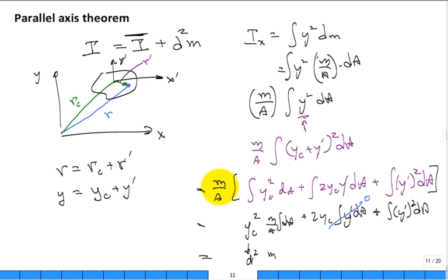When you bring in that m and a back into it, then we pick up the centroidal x-axis mass moment of inertia. So the non-centroidal mass moment of inertia with respect to the x-axis is equal to the equation that we just reestablished using the parallel axis theorem, d squared times m plus the centroidal mass moment.